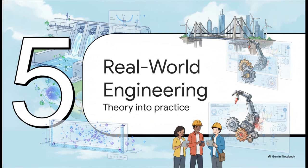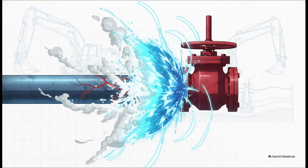Section 5, Real-World Engineering Applications, Bringing Theory into Practice. So why do engineers actually care about all this? Well, when dealing with compressibility, even though we know water is almost incompressible, that tiny microscopic fraction of compression can be extremely dangerous. For example, imagine a massive municipal pipeline. If a huge valve is slammed shut abruptly, the massive kinetic energy of all that flowing water actually forces it to compress slightly. That creates a sudden, violent, high-pressure shockwave known as a water hammer, and it can literally burst solid steel pipes wide open.